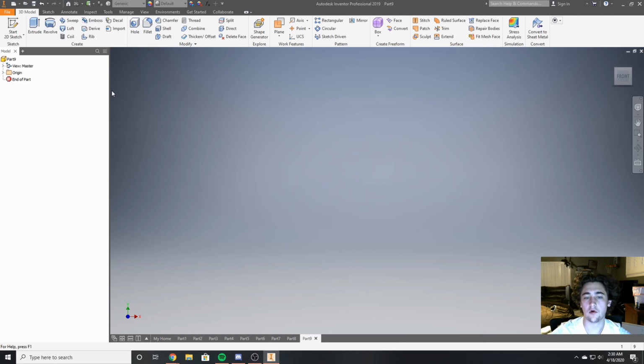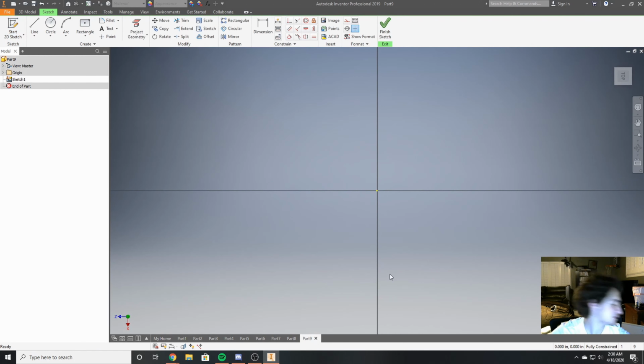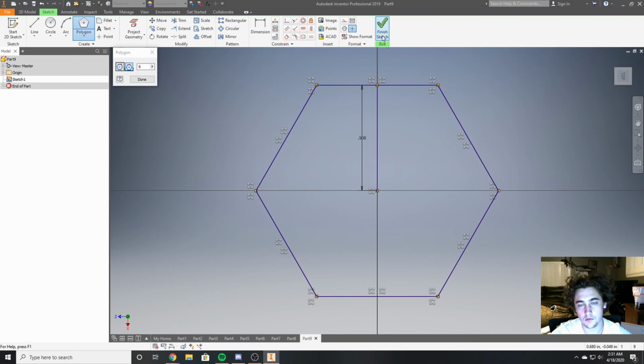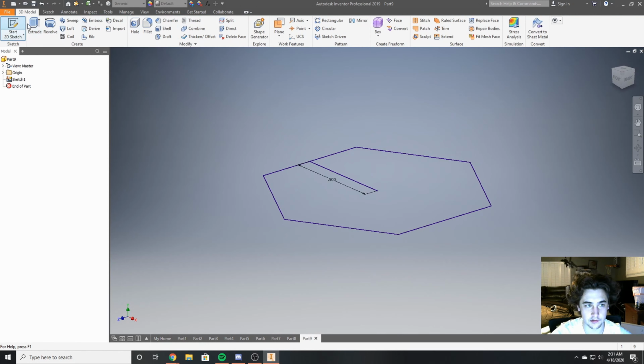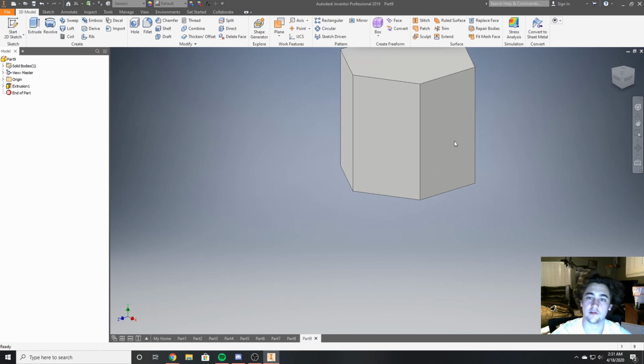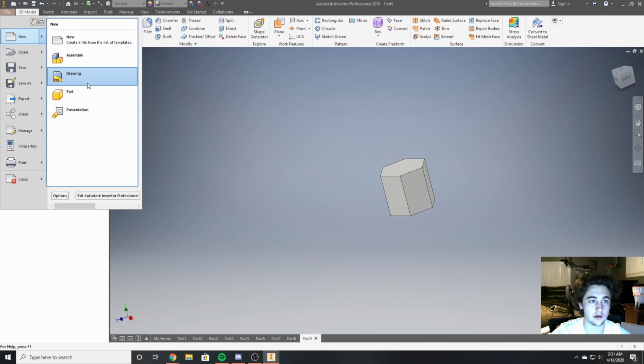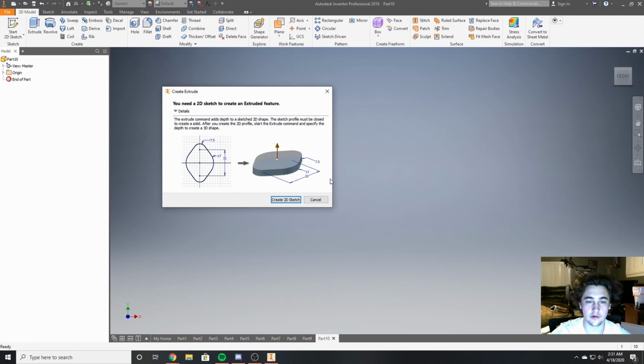New parts. Our third thing we wanted to create, look back at it, was a hexagon, 0.5 flat end, 0.5, polygon 6. Select this one to be flat. Boom. Finish this. I don't think I said how big to extrude it, so it's however size you want it. Boom. Alright, and the last one, the challenge one, let's do the sphere. Let's see how many people got that one right.